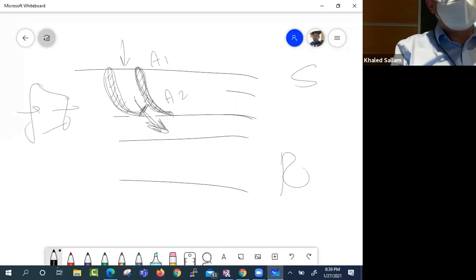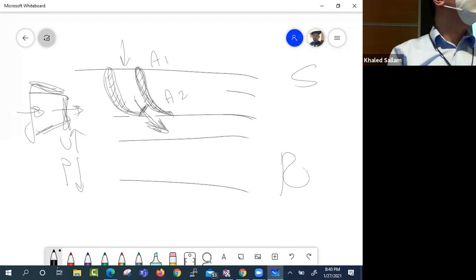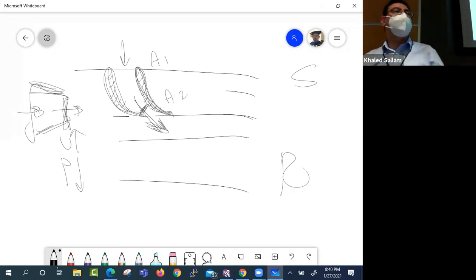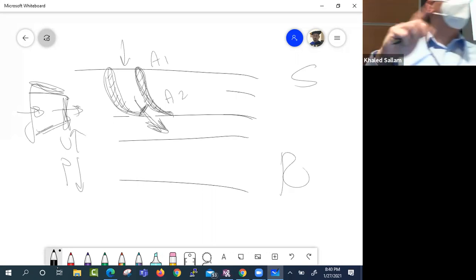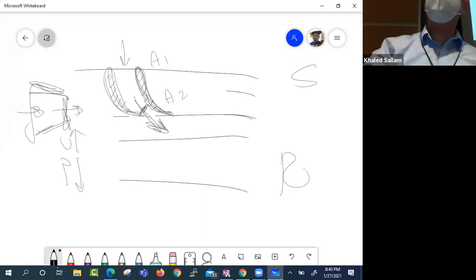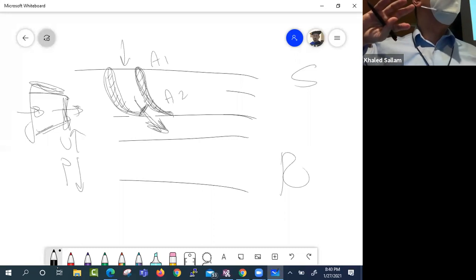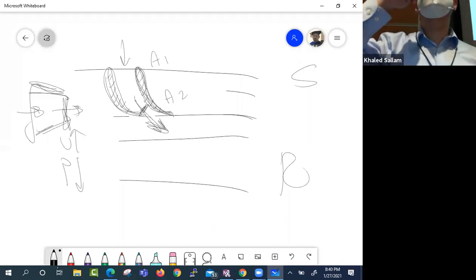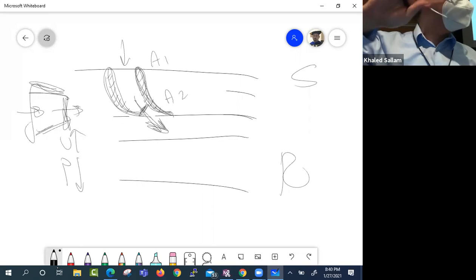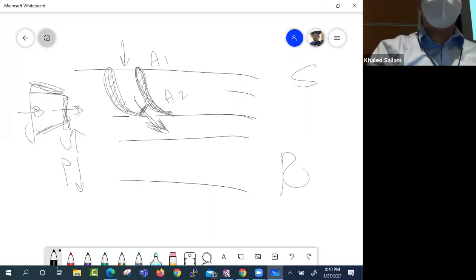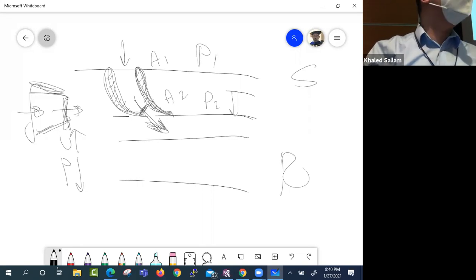right? When you leave at a very small area, what happens to your velocity and the pressure? That is the idea of the stator. Yes, we want to spin. I kept telling you about spinning, but not just let it spin, also accelerate it. We need the flow to leave the stator at very high velocity. Yes, with a twist, but also with very high velocity. That's why the pressure between V1 and V2 will drop in the stator.